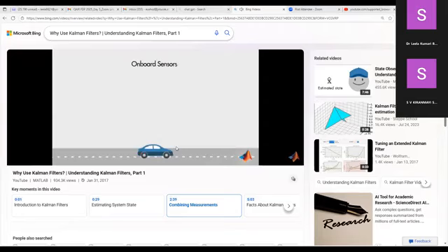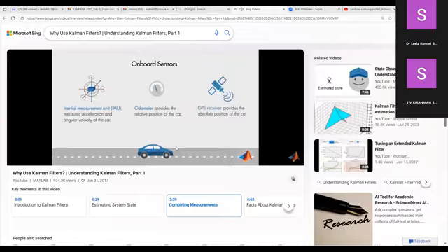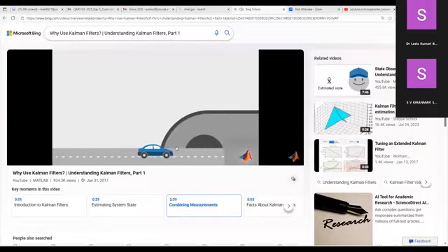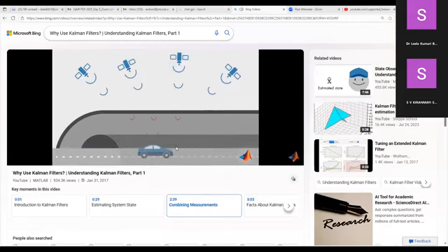The inertial measurement unit uses accelerometers and gyroscopes to measure the car's acceleration and angular velocity. The odometer measures the relative distance traveled by the car. The GPS receiver receives signals from satellites to locate the car on Earth's surface. If you live in Boston as I do, you've got to travel through the Big Dig, a very, very long tunnel. And in the tunnel, it gets harder to estimate your position through GPS, since the receiver's line of sight to satellites is blocked and GPS signal is weak.